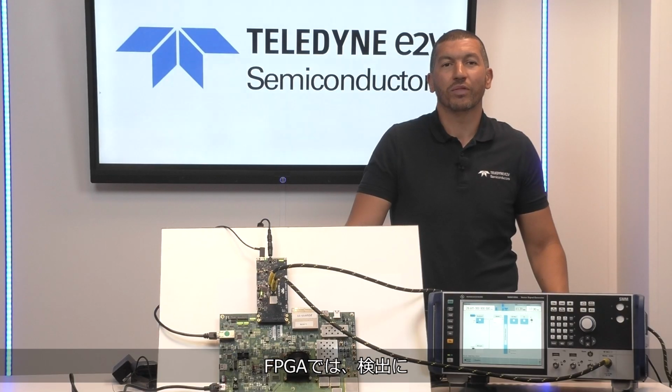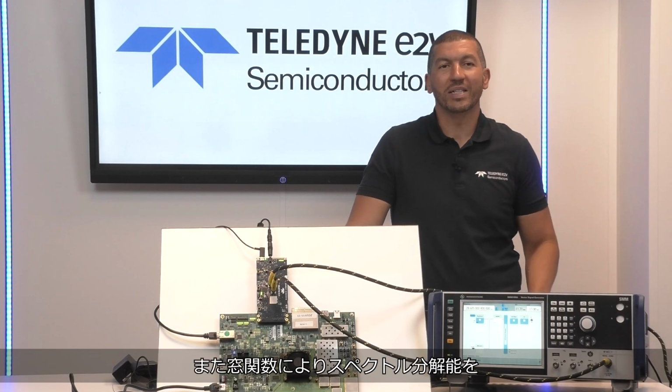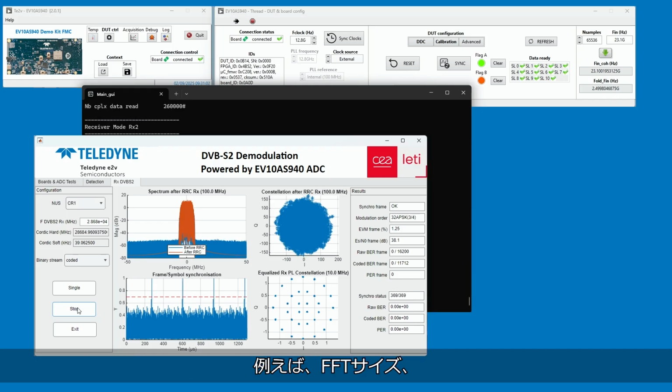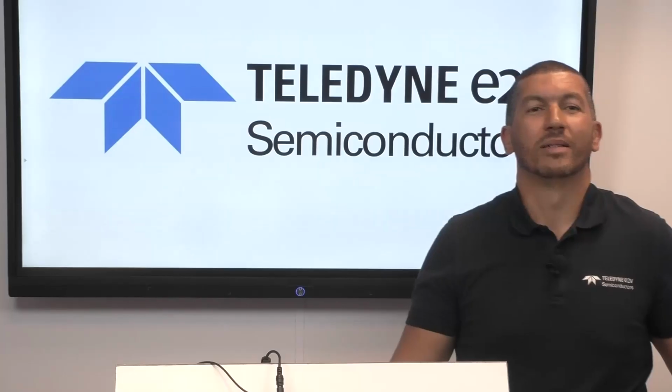The FPGA performed detection using FFT-based channelization, proceeding by windowing to improve spectral resolution. The GUI allows users to configure parameters such as FFT size, compression ratio, window type, and detection threshold. Detection is based on accumulated FFT power compared to calibrated noise reference.